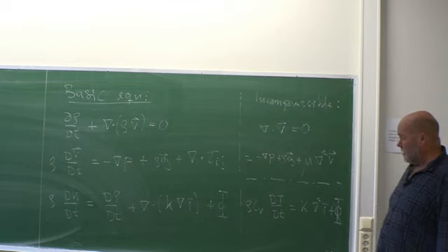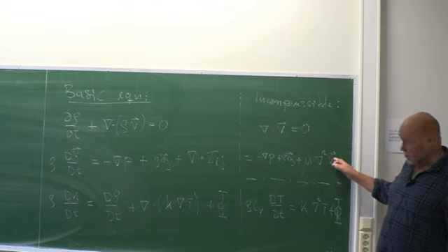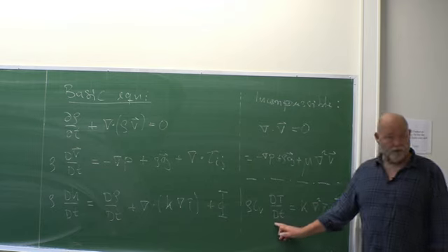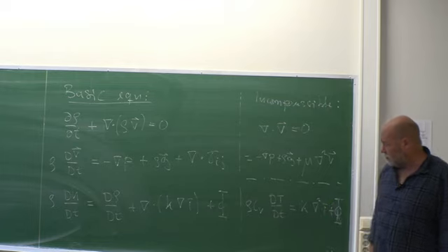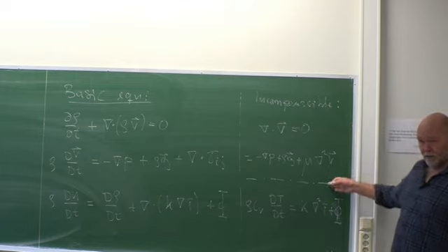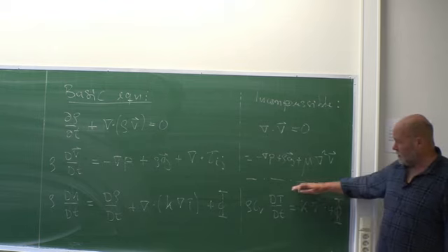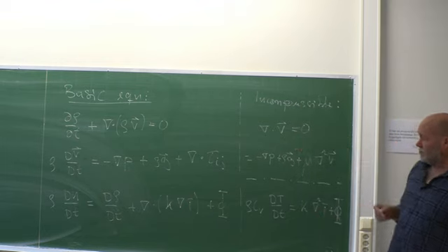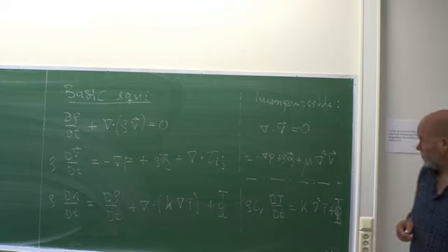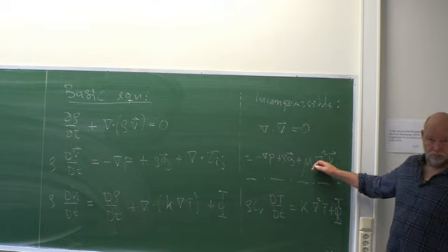They stand alone. After you have solved the velocity and the pressure, then you can calculate the temperature if you want. That's an option, but you don't need it for anything. So they are totally decoupled. Here you'll have 4 unknowns in 3D: 3 velocity components and the pressure. That's it.